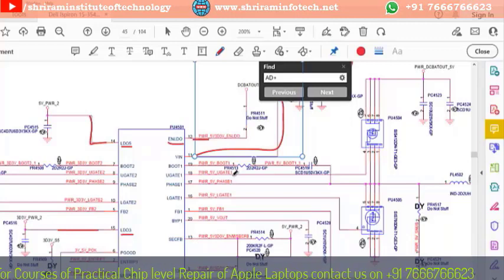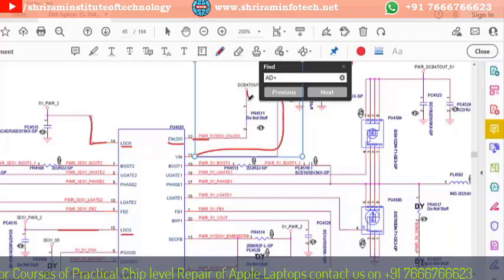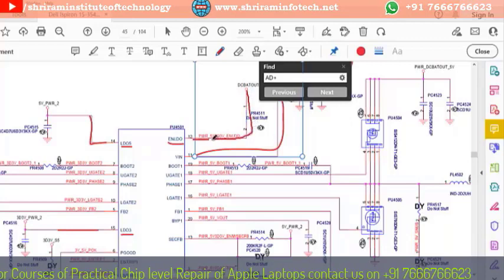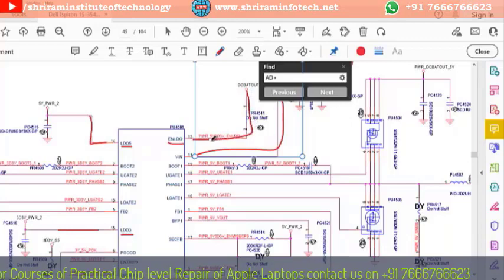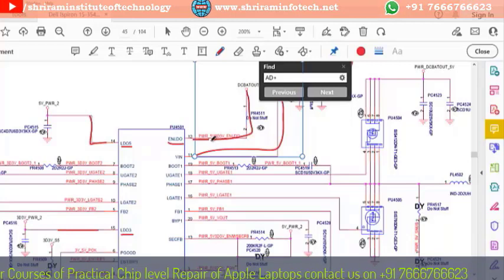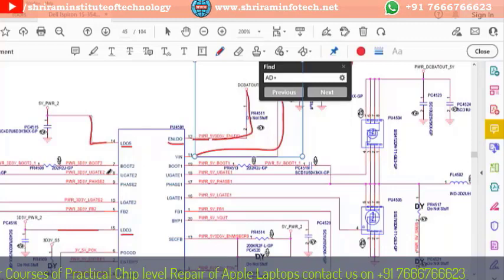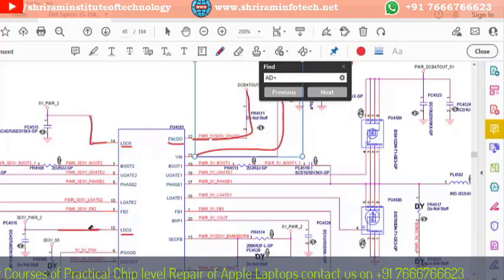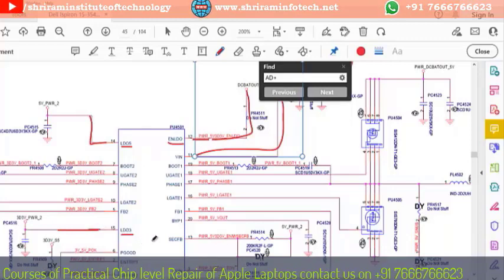So here you should get 3 volt. Now that DC bat 18 volt is directly given to pin number 12, that means above 3 volt is the enable signal. Once pin number 12 voltage is coming and 11 voltage will come, then 3 volt will come out. Okay, so we'll go to the board viewer and see.